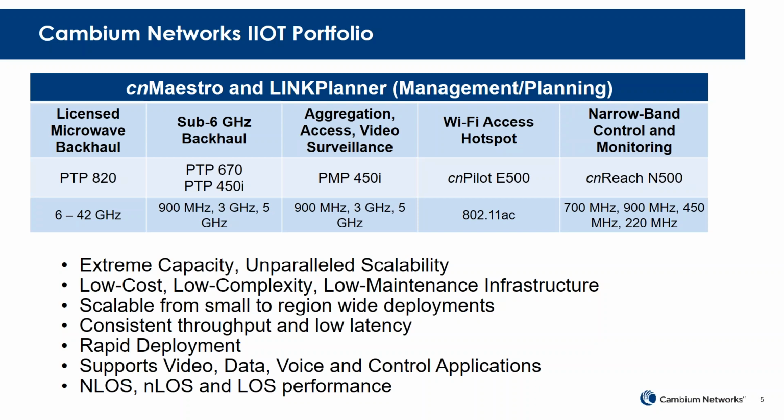Video surveillance can be well handled by our PMP450i. This is a point-to-multipoint solution. So think of it as a star topology where I have a series of access points. Each can connect up to perhaps 200 endpoints, and then each of those endpoints can be connected to a number of video cameras. So I can bring lots of video surveillance capability back to a central point. And of course, I can share that same infrastructure between video and other types of access requirements.